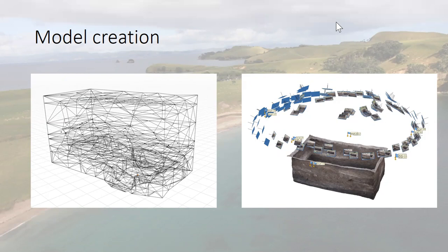And then it was put into the open source CloudCompare to try and create a stable surface from the SLAM data, which it wasn't quite able to do. So we used the proprietary Geomagic software, Geomagic Wrap, which did the job by averaging the points. Effectively, there weren't enough stable architectural features in the area, which is a natural area around the trench, to create a solid surface for the trench. We got one that we could work with by averaging it, but it was a pretty aggressive filtering tool.